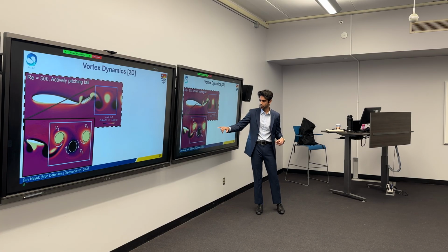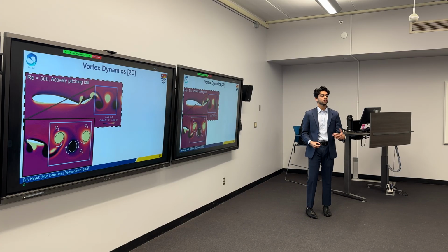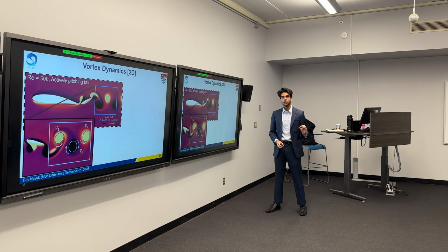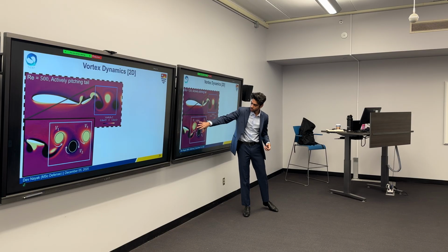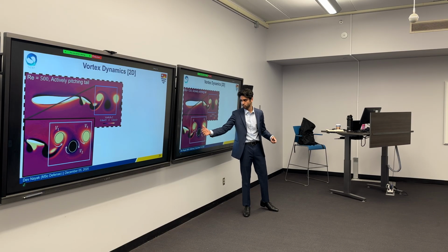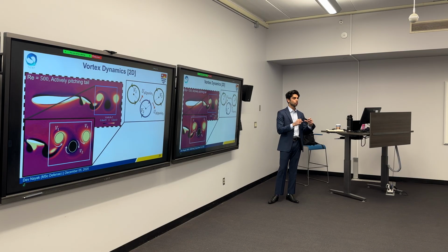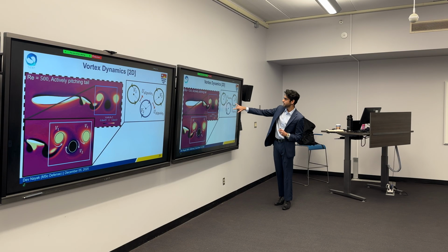So the positive vortex would be rotating anti-clockwise, and the negative vortex rotates clockwise. And what does that do? Whenever the vortices rotate, these two vortices contribute towards a net dipole velocity. So it creates something like a velocity component between those two vortex structures. A similar effect is observed between these two other vortices.